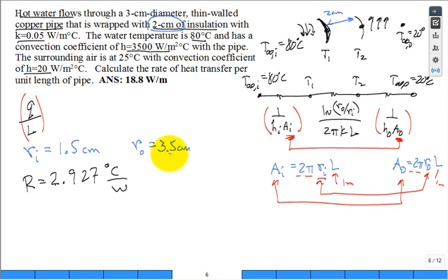And when you go back and evaluate, this is like 0.1% due to the convection on the inside, and about 92% conduction through the insulation. And then this was about 8% for the convection on the outside. So you get a sense of the magnitude of those three components.